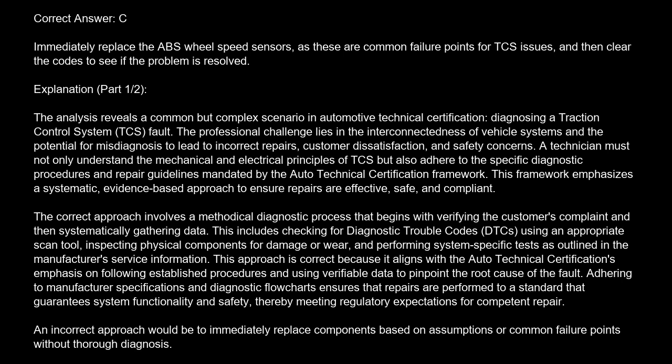The correct approach involves a methodical diagnostic process that begins with verifying the customer's complaint and then systematically gathering data. This includes checking for diagnostic trouble codes, DTC, using an appropriate scan tool, inspecting physical components for damage or wear, and performing system-specific tests as outlined in the manufacturer's service information. This approach is correct because it aligns with the Auto Technical Certification's emphasis on following established procedures and using verifiable data to pinpoint the root cause of the fault.